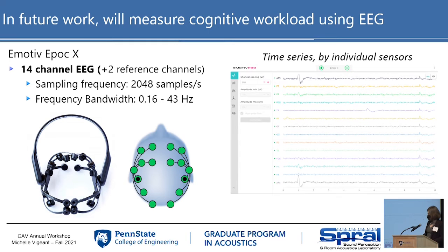This brand is Emotiv, and it's a headset that looks like that. Each pad, there are felt pads for each electrode that get soaked in a saline solution, and that allows for conductivity. The software that it comes with gives us a good way of checking how well it's connected and the data quality, and then we can get a series of output that can be analyzed by using different wavelengths to measure for things such as attention or distraction, and that type. Attentiveness is one of them.